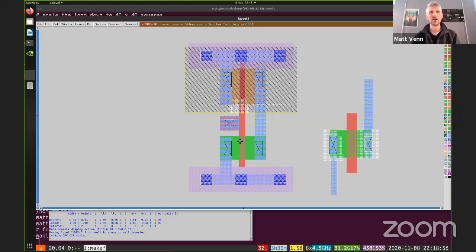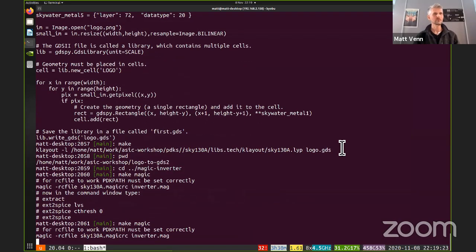So you can see how you could build up a shape like this. And we've got the N channel here, the P channel here, the polysilicon gate, the input connector, the output connector. And then the way this structured bit at the bottom and the top makes this easy to duplicate and make arrays of and lay them out in big patterns. And that's what the OpenLane ASIC tool flow makes use of. So let me just quit this and start it again.